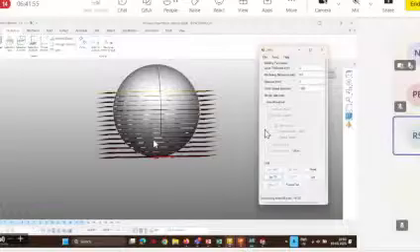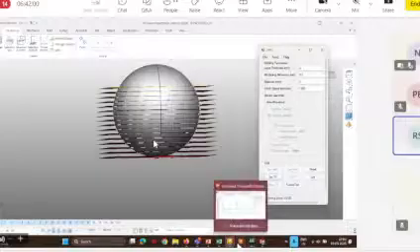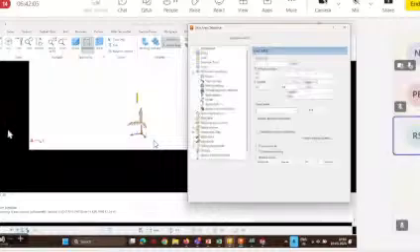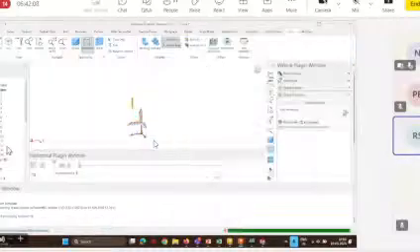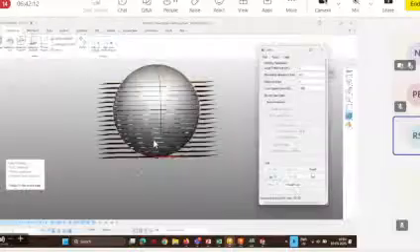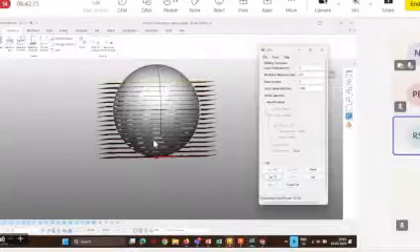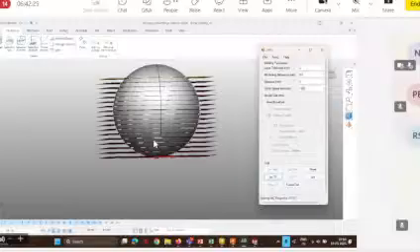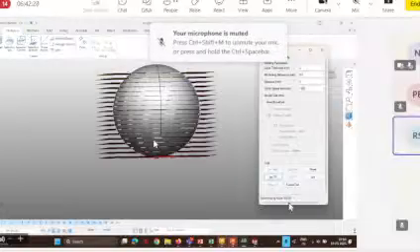And yeah, it's on the 14th layer now. If you come back to PowerMill, you can see it has already generated the NC files as well, up to the 15th layer. Right now we are generating them separately, but it is also possible to generate a single NC file, so that we can put it directly in the machine and print the entire part in a single go. So it's writing again.